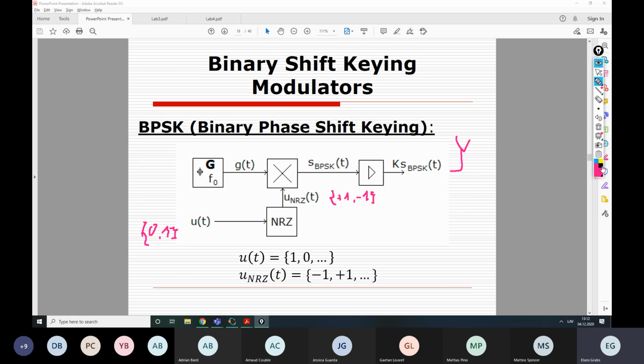Here I'd like to once again mention that most often the assignment for NRZ is performed as 1 is converted to -1, and 0 is converted to +1. Of course, it's not really important, but this assignment provides us additional benefit for the XOR operation.